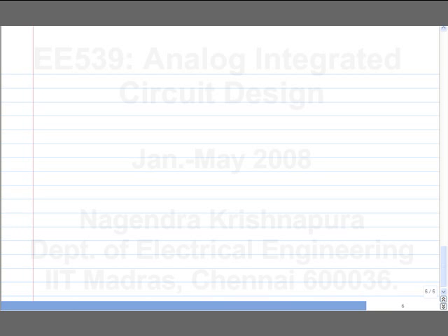No, this has nothing to do with differential circuits, right? In any circuit, if you find two voltages at identical potentials, you can connect them together. That's what you learn in circuit theory, right? Node voltage, the equations will not change, isn't it? Any circuit. So let me maybe redraw this. I have, let's say, R1, R2, and I excite it with some voltage.